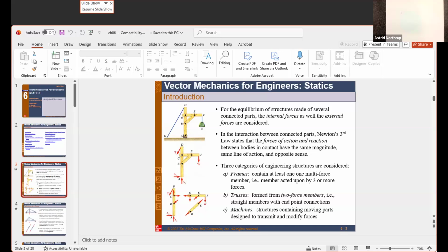So when you have a reaction, like right here, there is some kind of a force at A. We divide it up into A sub X and A sub Y, just because that completely describes the force. If you have a weight, it's purely a Y directional force because it's just something responding to the force of gravity, and everything else has to occur along the direction of the structural members.